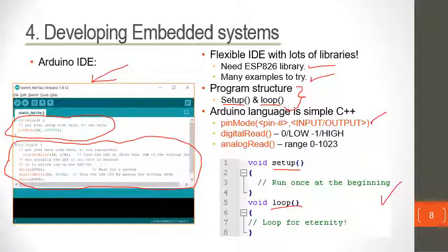And then it could have, for example, a function which is already written in, that would be digitalRead. This would be equivalent to reading what the input is at the particular pin. For an analog pin, you can have analogRead, and Arduino will immediately know that you want to read the value of the ADC linked to that particular input pin.